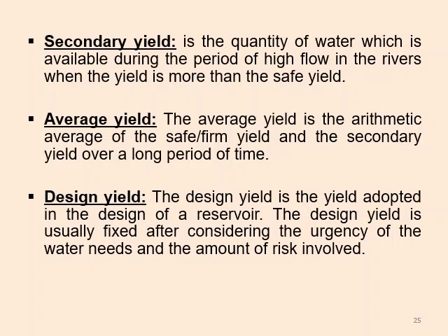Average yield is simply the arithmetic average of safe yield and the secondary yield for a long period of time. Now design yield. Design yield is the yield adopted for the design purpose of a reservoir. Design yield is usually fixed after considering the urgency of the water need, the water demand, and the amount of risk involved to construct a dam and reservoir.